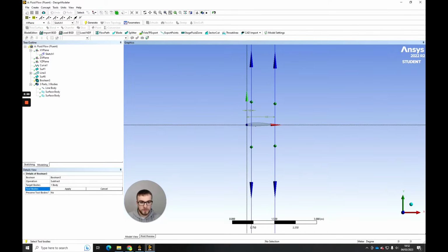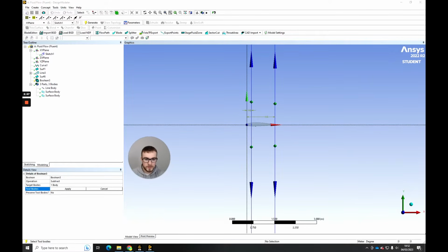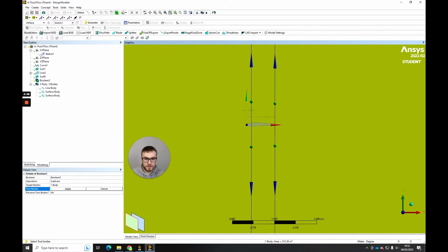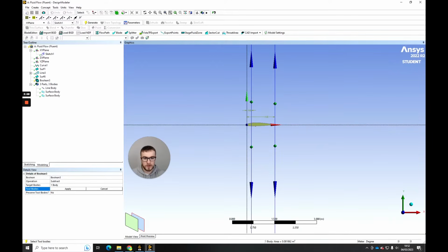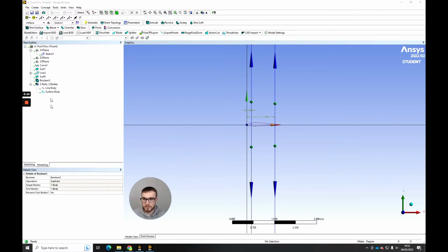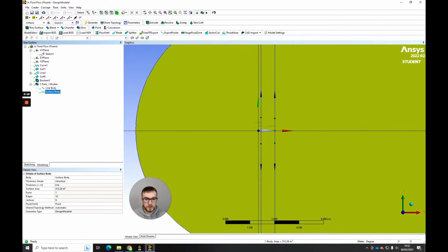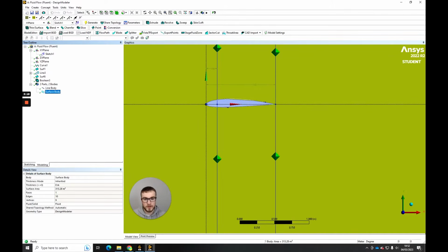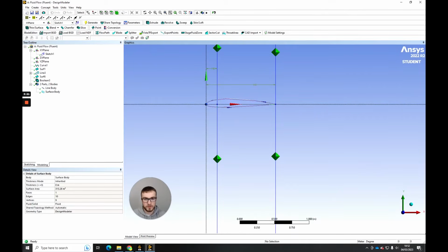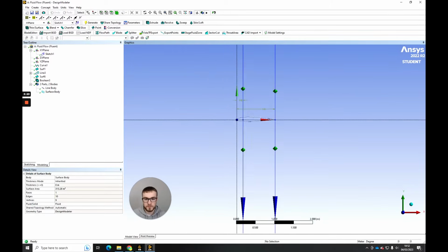Now to select the airfoil surface, we need to click the airfoil here, but you'll see ANSYS actually selects the fluid surface we just created. We don't want that. We want to select the airfoil behind that. So we need to click this plane here and you'll see it highlights the airfoil surface. Then I hit Apply and then click Generate. And you'll see we're now left with a fluid surface with an airfoil shaped hole in the domain, and this hole is representing our solid airfoil, of course.